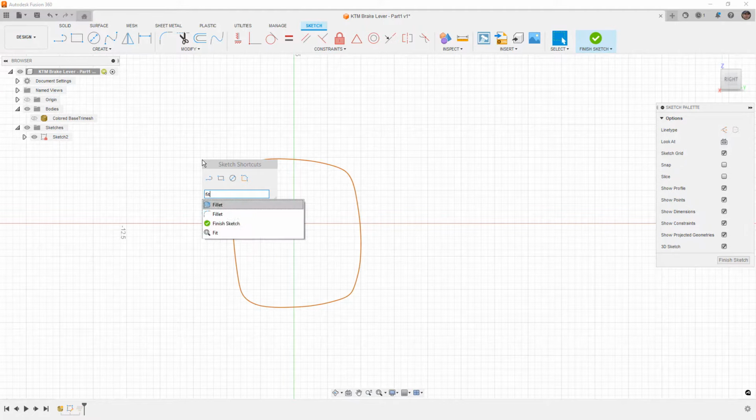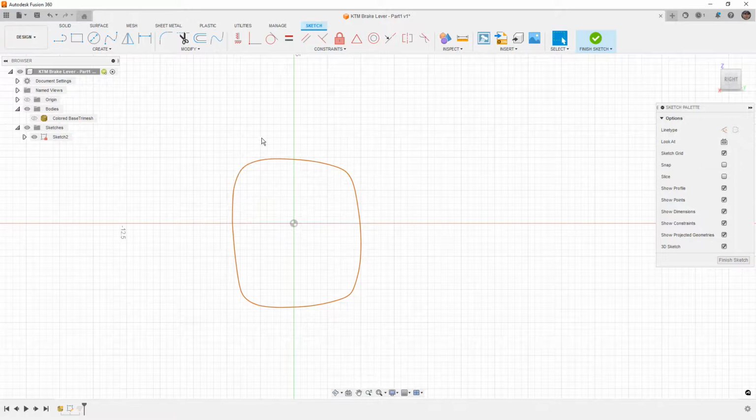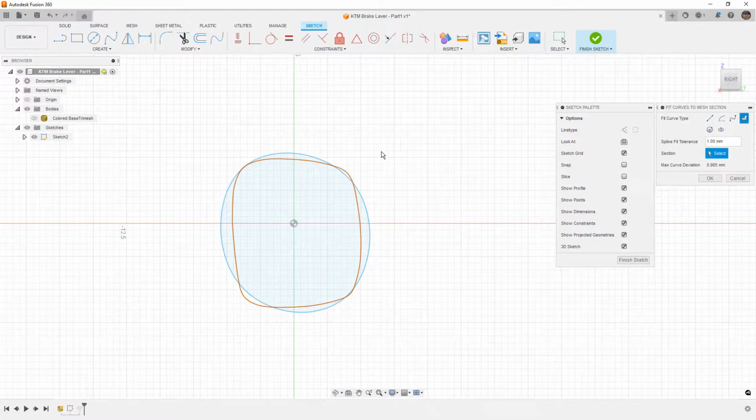And if you say fit mesh curves and you use a little up arrow, which will show here, you can put it on the shortcut menu, which just pops up wherever the mouse is. And that way it just speeds it up a little bit. So again, you can see here, plus or minus a millimeter is kind of way too much. If we do plus or minus 0.04, that was the resolution of the scan. And I click that and say, okay.